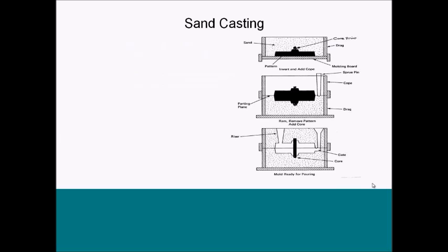We're going to use the following diagrams to talk you through a typical sand casting process. So the first step is for us to develop what we call a pattern. And a pattern is basically a reproduction of the part that we want to actually manufacture with a few small changes. So this is a wheel that we're making here, which is quite solid, and we can see that there's a bit of a boss on this wheel here. And we've also got something on the tip there called a claw print, and we'll talk about that in a second.